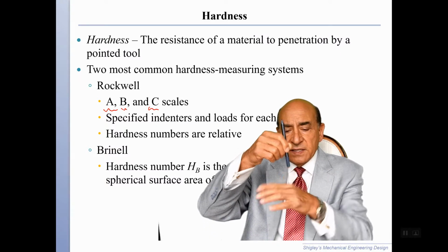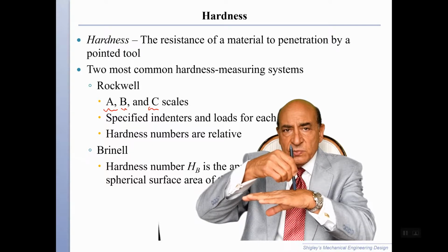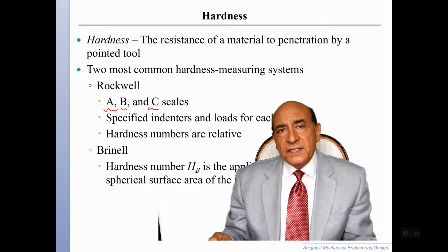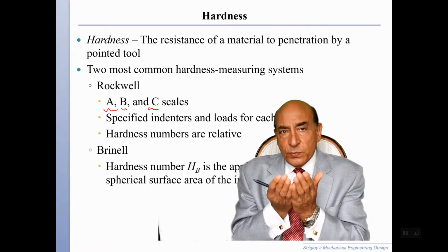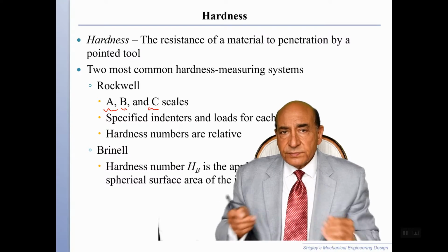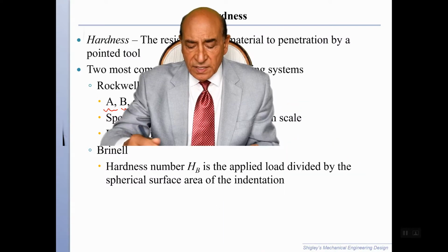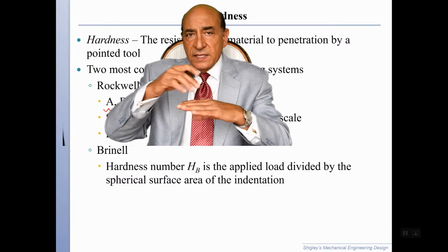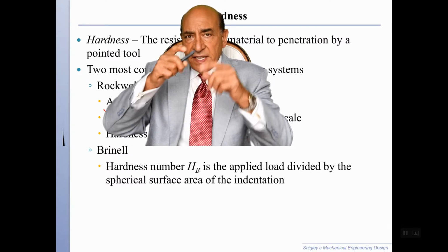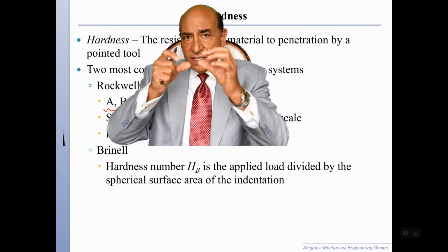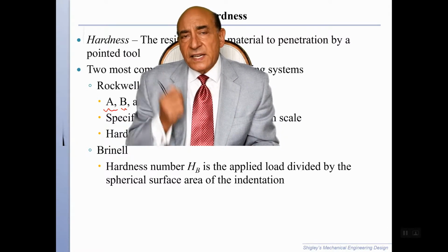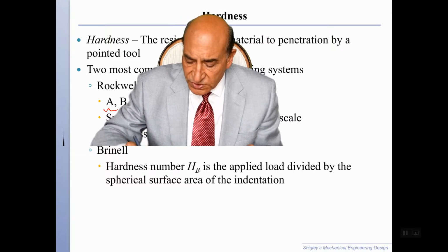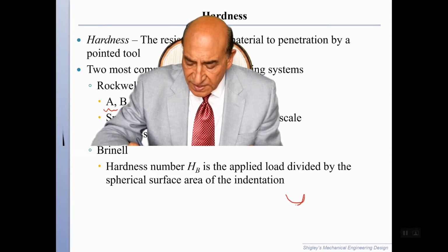at the end. So you have a hemispherical tip, and you push hard on the material, and you see how far the hemisphere is going to penetrate into the surface, and the relationship between the load, and then the hemisphere is going to have a contact area. So the contact area can be measured. So if you measure the load and then you divide it by the contact area of this hemisphere, I'm going to show it here.